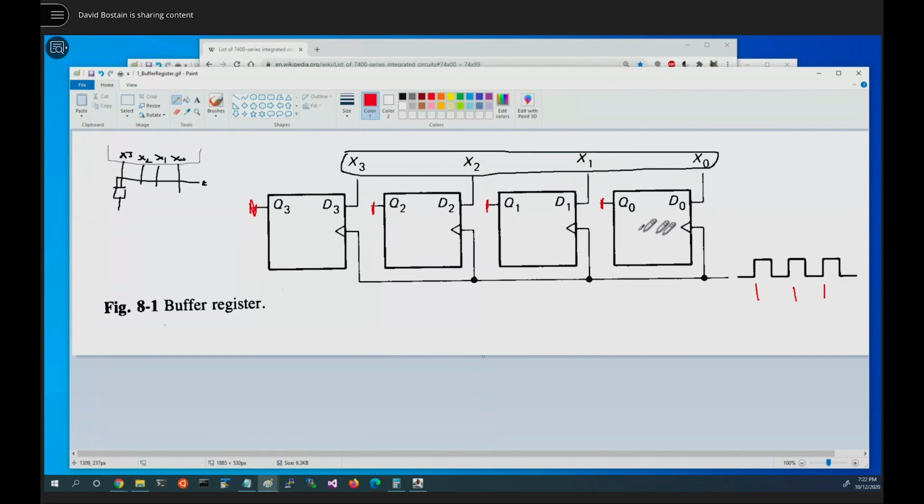Now, if we want to have predictable values in here that represent what X means at a particular point in time, we need to make sure that X is available. Now, how early does X have to be available relative to this clock edge? Anybody want to take a shot at answering that? Just gotta take a wild guess. Would it be 22 nanoseconds? Well, give that a name. What is it? 22 for this chip.